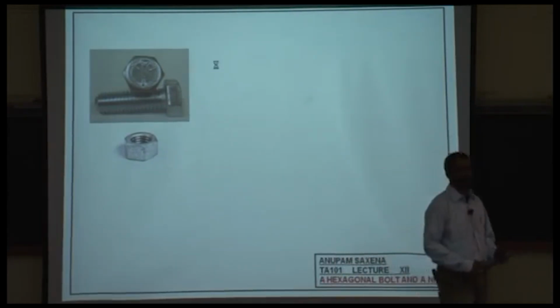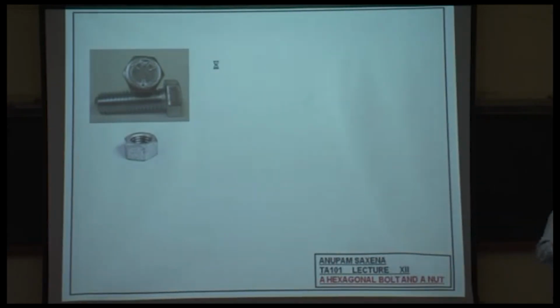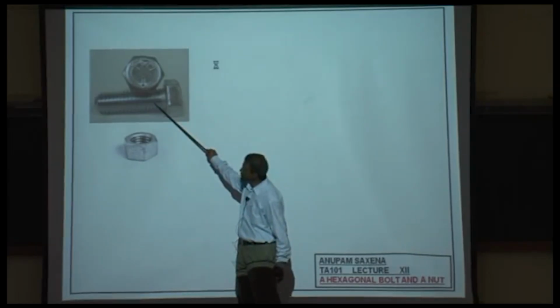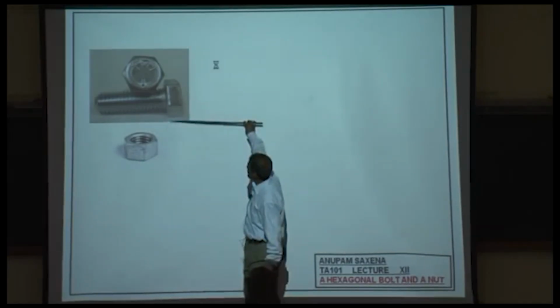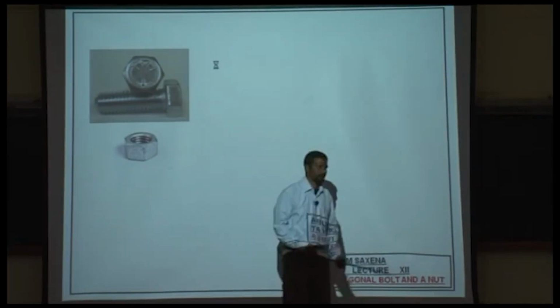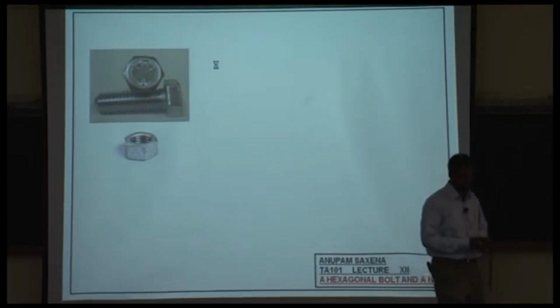And you have to figure out, by convention, that the size of this bolt depends on D. The minor diameter of the threads also depends on D. This here depends on D, and I'll show you how, using one of the conventions that people tend to follow.